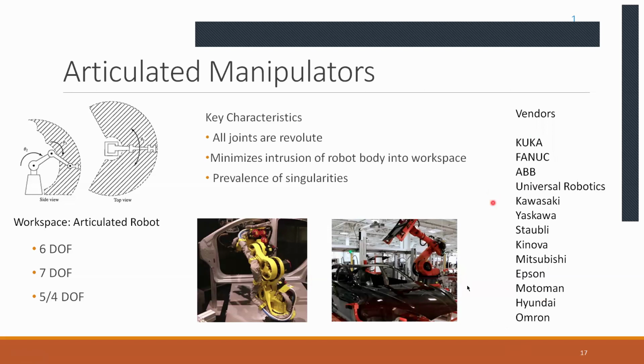With these other non-backdrivable robots, if it works alongside a human and makes a mistake, it would come crashing into the human and injuries will definitely occur. But with collaborative robots, with that backdrivability, it will not crash, but rather decelerate itself upon contact.